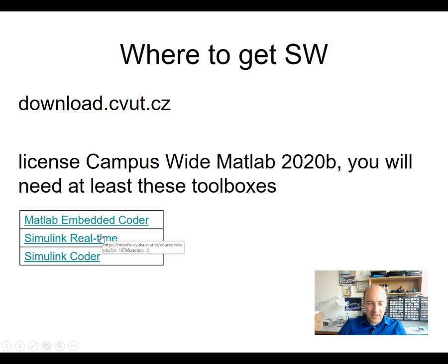You will need at least those 3 toolboxes: MATLAB Embedded Coder, Simulink Real-Time, and Simulink Coder. As you probably know, there are many toolboxes in MATLAB. You can also install them all. It's up to you if you need them or if you have enough space on the hard drive.